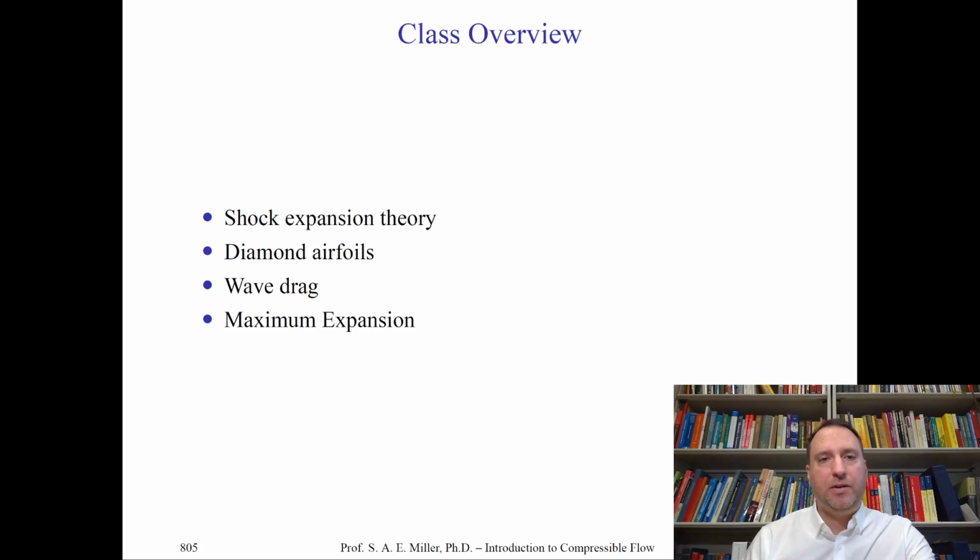These are simple airfoils to illustrate the most important concepts of supersonic flow, where systems of shock waves and expansions occur. Then we'll talk about the all-important idea of wave drag, which dominates drag at high speeds. And then we'll do an asymptotic analysis for the turning angle going to infinity of the Prandtl-Meyer expansion waves to find the so-called maximum expansion of the flow. Let's get started with these important concepts.